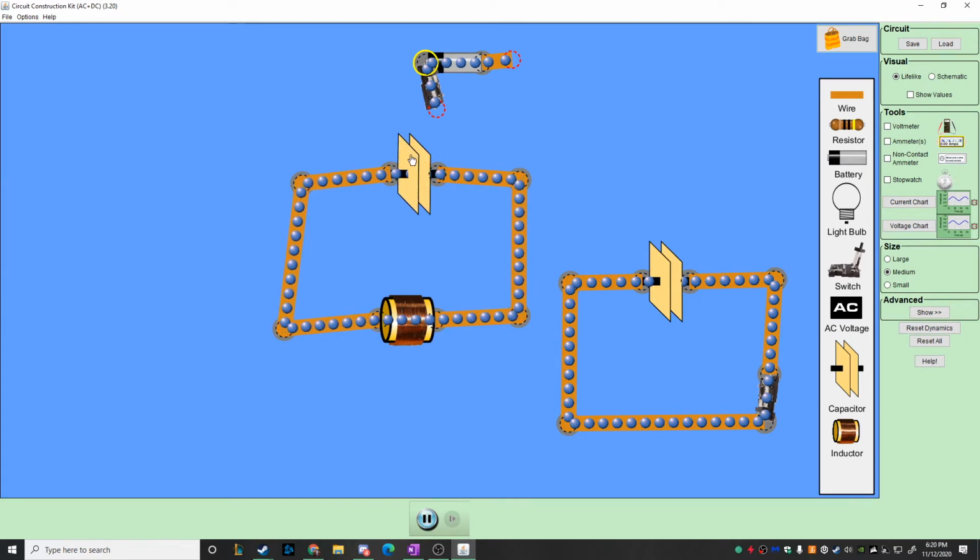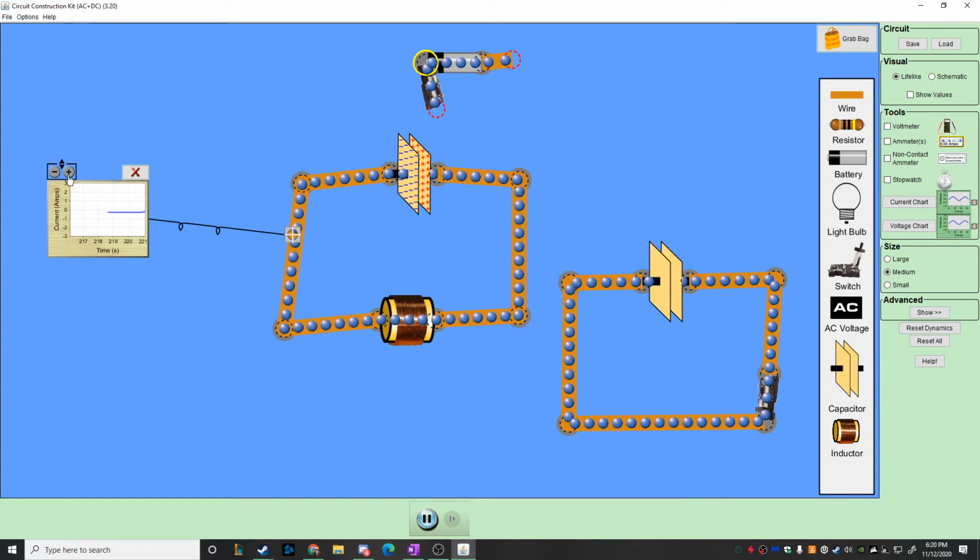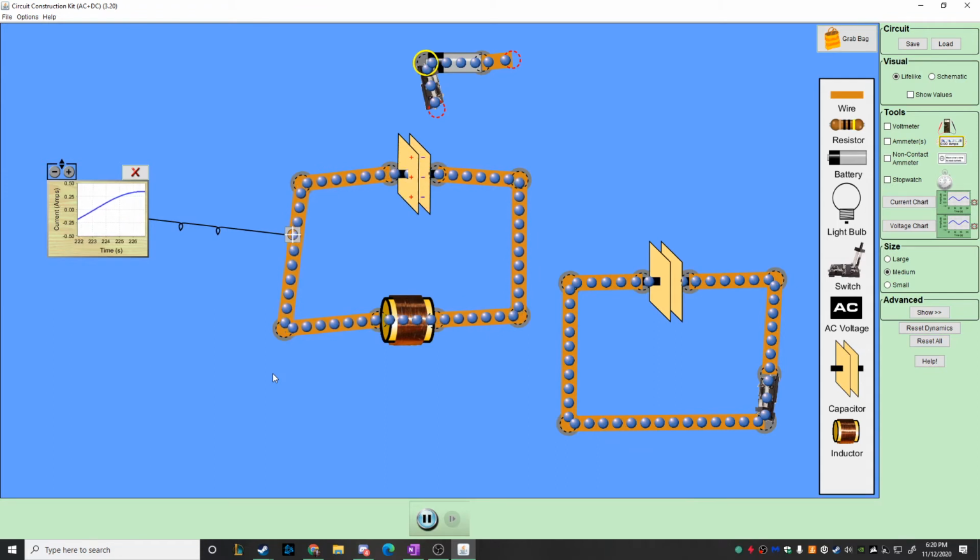So you start off with energy stored in an electric field. That energy then goes directly into the inductor, which stores it in the dense magnetic field. And then the magnetic field of the inductor can keep the charges going effectively, right? So an inductor has the effect of stopping you from having... Oh, and we can also do one other thing here. I can pull this current chart in here, and we can see that it's sinusoidal. The idea is that current starts to flow, and eventually it's going to stop, right? But the inductor tends to make it keep going.